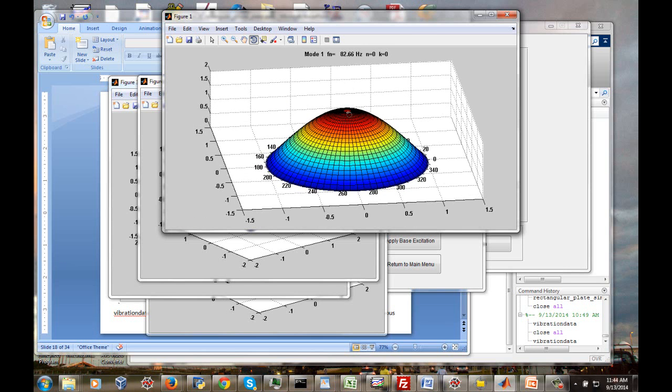The hoop stress disappears at the center of the plate. So that's kind of like a singularity point, or whatever you want to call it, a point where there is no hoop stress. But then at all these other points, intermediate, and even out to this outer boundary here, there's stretching going on in the circumferential axis or tangential axis, whatever you want to call it. So there is hoop stress.